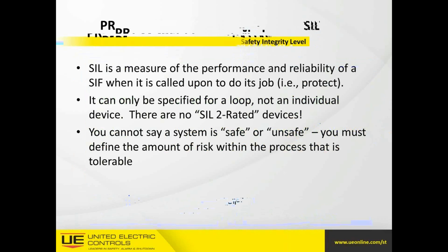So this safety integrity level that we talked about just briefly already, SIL, we've heard SIS, we've heard SIF, safety integrity function or safety instrument function. We've heard about LOPA. This SIL piece of the puzzle is very important, and it stands for safety integrity level. It is a measure of the performance and reliability of the individual safety function of an instrument. So SIL is a measure of performance and reliability of the SIF when it is called upon to do its job. Now keep in mind that these devices may sit for 5 years, they may hopefully sit forever and never be called upon. But we need to know that they're going to be functional and working when they are called upon. And we're going to talk about some of those challenges as we move through here.